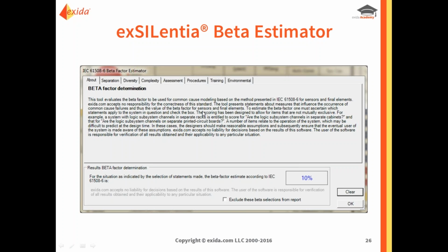From a logical point, yes, absolutely, when beta increases, you would expect PFD to increase as well, but look at it from a complete system modeling perspective. Beta does have a negative impact on your 2 out of 2 configuration, but it has that negative impact on that portion of the configuration for which it was designed. 2 out of 2 is designed to reduce spurious trips. Adding common cause will negate the benefits of the redundant configuration with regard to spurious trip protection.